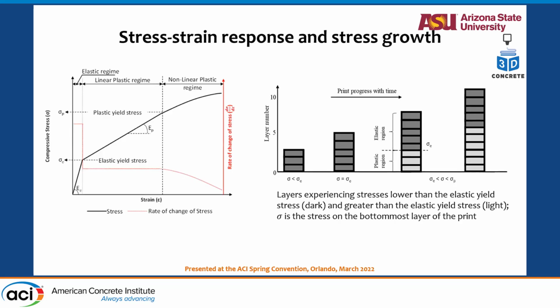So we did a bilinear stress strain curve, by doing plastic response at extremely slow deformation rates, with extremely slow loading, so that you're not missing what is happening when deformation happens in very plastic mixes.